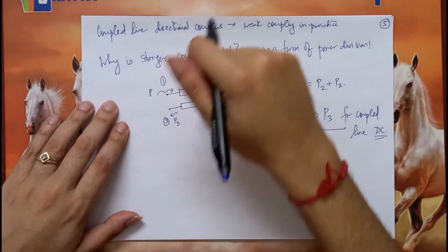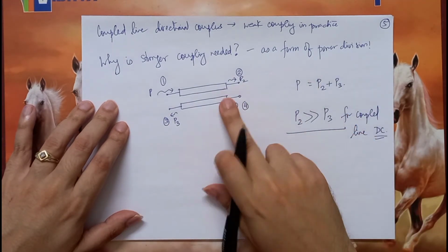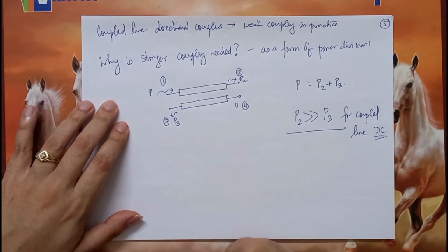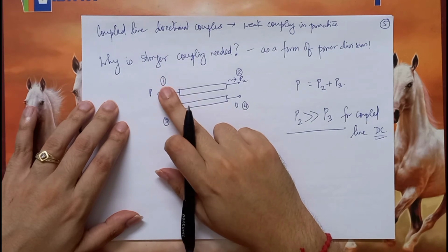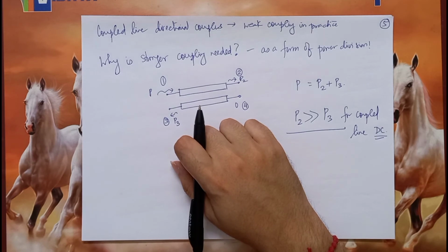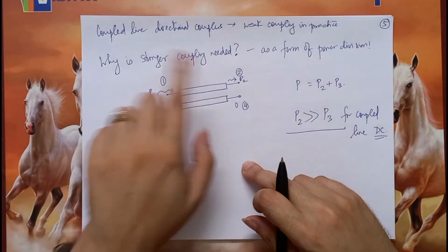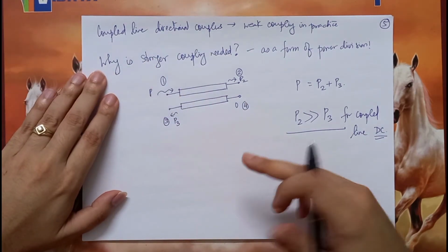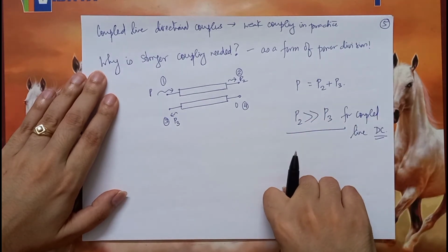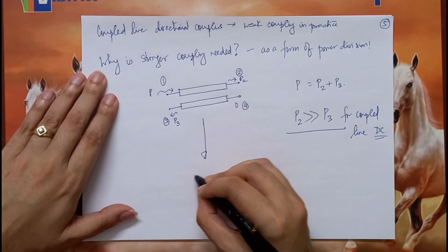we cannot deny that the directional coupler provides us a way to divide power by having a circuit that is matched, that is reciprocal, and at the same time lossless. Because we have proved that it can be matched at all ports as long as the Z0, Z0E and Z0O relation is maintained. It is reciprocal by virtue of its structure, and lossless because it has no resistors whatsoever. So this gives us a prospect of a lossless power divider also.